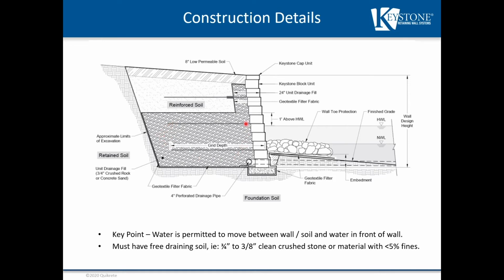If we don't have this free draining aggregate, we're not going to withstand that sudden drawdown. We're going to get hydrostatic pressure built up behind the wall. So we want to keep this as a singular crushed stone aggregate.